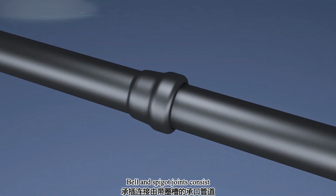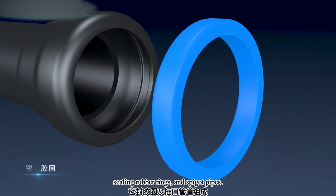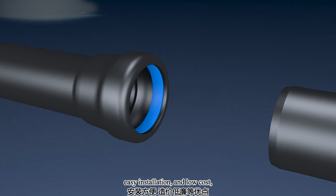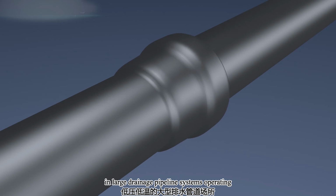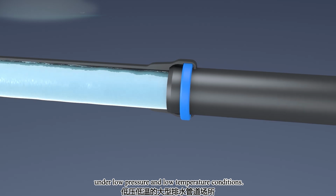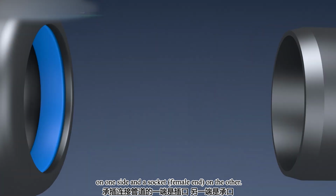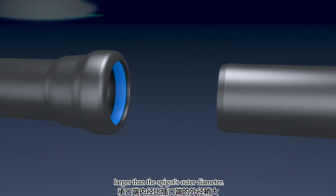Bell and spigot joints consist of bell pipes with circular grooves, sealing rubber rings, and spigot pipes. Bell and spigot joints offer advantages such as quick connection, easy installation, and low cost, making them widely used in large drainage pipeline systems operating under low pressure and low temperature conditions. A bell and spigot joint in piping has a spigot, male end on one side, and a socket, female end on the other, with the bell's inner diameter being slightly larger than the spigot's outer diameter.